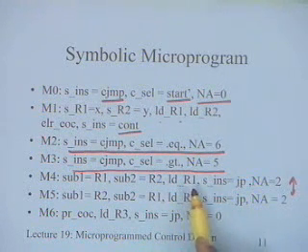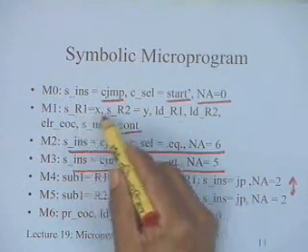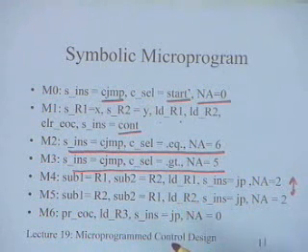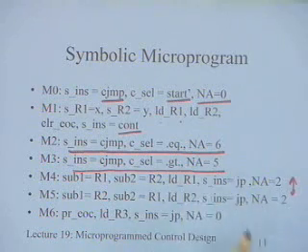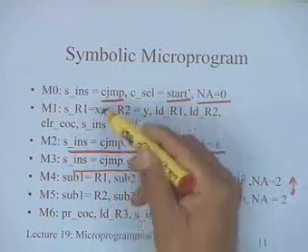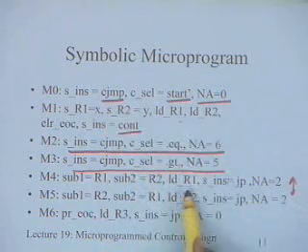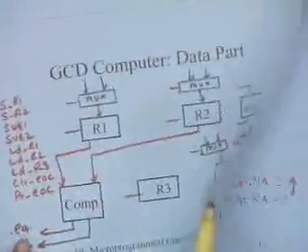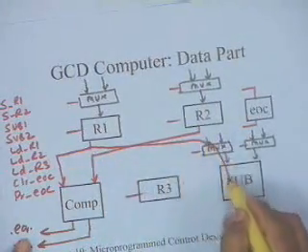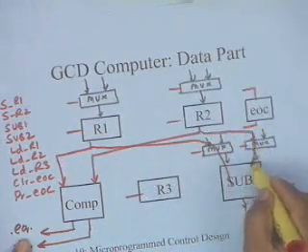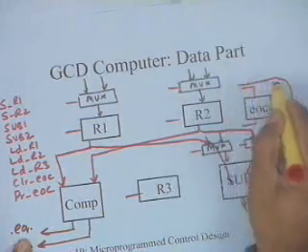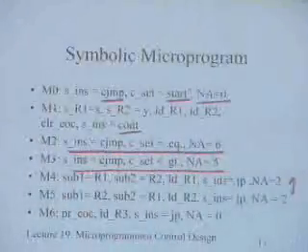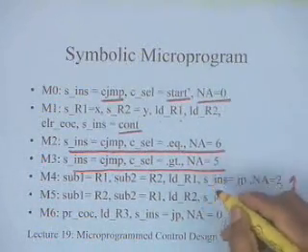And now remember why that load thing was required at the end. You can see that in this case no operation was being performed. But in this case, at the end of the clock cycle I need to load, because the subtractor will take time to subtract. So I have to have the clock cycle delay to perform the load. Previously I was just loading, and the delay was only through the multiplexer. Here it is not just the multiplexer but also the subtractor. So this whole path, I am going to choose now R1 as an input, multiplexer, subtractor, R2 as an input, multiplexer, subtractor, and this. So one more control signal is missing here.